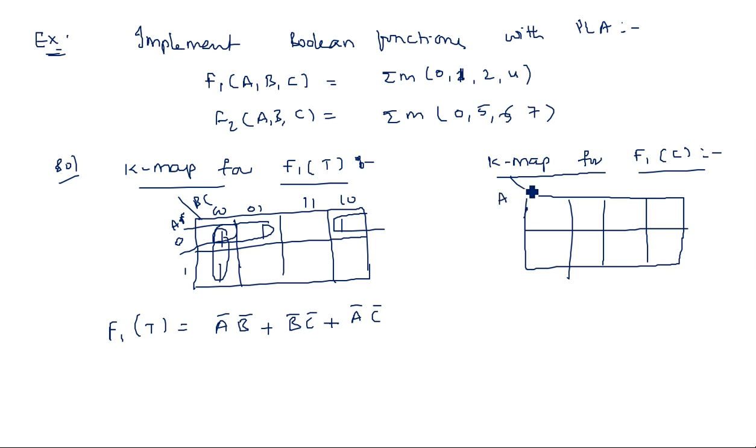Okay. So A, B, C, 0, 0, 0, 1, 1, 1, 1, 0, and 0, 1. Here whichever is left vacant, that we have to consider. Ones are not there means zeros are there. We map these two, map these two, map these two. So F1 complement form, nothing but you can write it as F1 bar, is equal to AB plus AC plus BC.